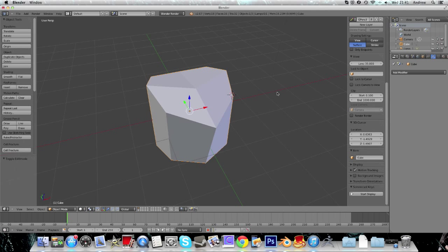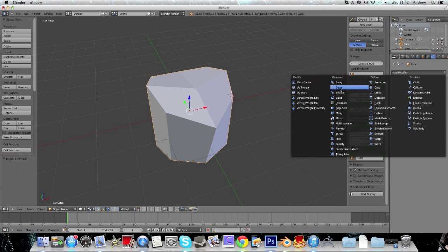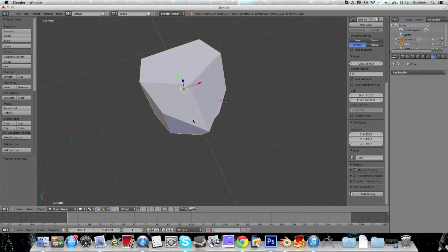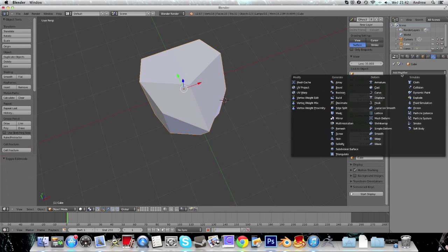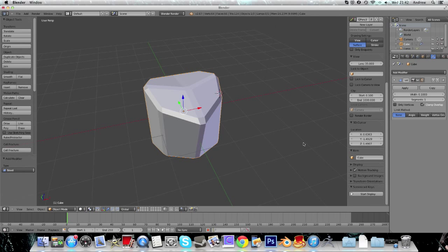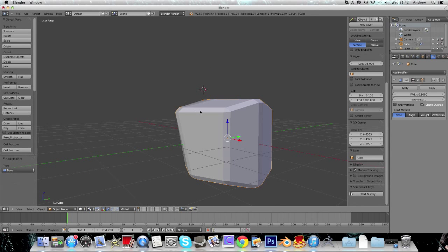If you've seen any of the videos, then you'll know that we are looking at modelling, and we're going to look at the Bevel tool to start off with. If you don't know what beveling is, we may look at the modifier, which is just called bevel. I've got a random shape here, just a cube with some ring loops. You add the bevel modifier, and right there we can see what it does. It flattens the edges, and if you've got any sharp edges it's going to bevel them, which helps make the shape look even nicer depending on what kind of effect you're going for.